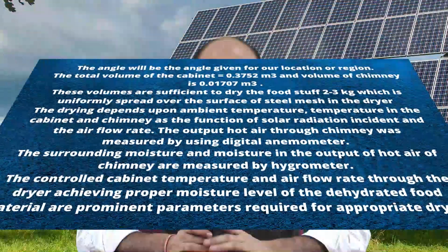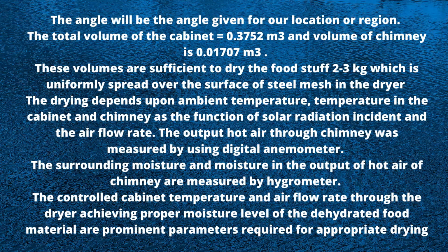The transparent glass cover makes up the cabinet, due to which the solar radiation incident on the glass cover during the daytime is collected to the maximum possible extent, employing solar energy effectively. The angle will be the angle given for the location, that is the angle of latitude. We can use the angle of latitude for that inclination.